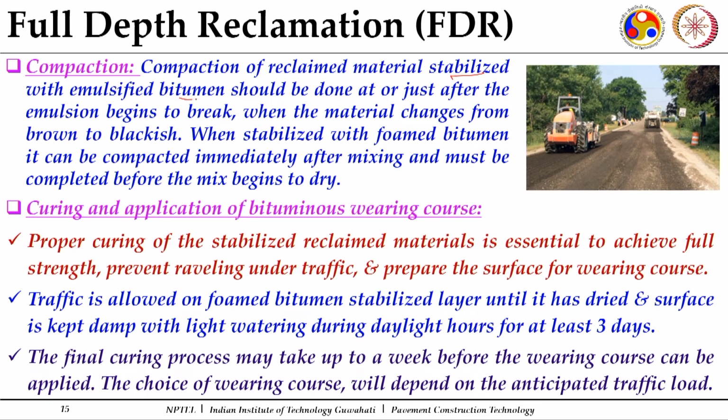and during the compaction part, specifically when emulsions are there, one important concern is that the compaction has to be completed by the time the emulsion starts breaking, because otherwise the mix will become stiff and difficult to compact. Whereas when you are using foamed bitumen, we prefer that the compaction should be completed by the time the mix becomes dry enough, because you have the time before it becomes stiff. So, for foamed bitumen, we prefer it by the time the mix becomes dry, and in the case of emulsified mixes, we prefer to complete it by the time the emulsion starts breaking.